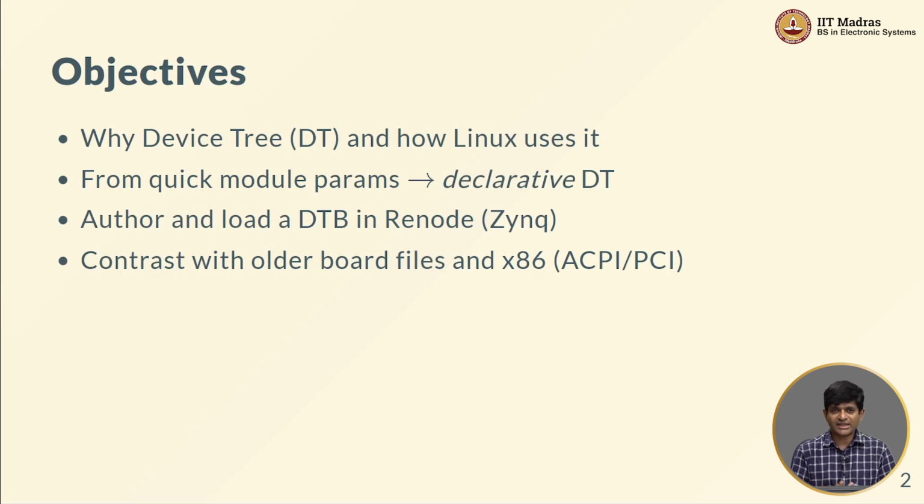The advantage of that, as we already discussed, is that there are already some standard functions in the C standard library to open files, close files, read from files, write to files and so on, which means that pretty much any device, if we can make it look like a file, we can reuse those functions in order to get a much bigger range of functionality than what would be possible if we had to individually go and peek and poke individual registers that are present in the device.